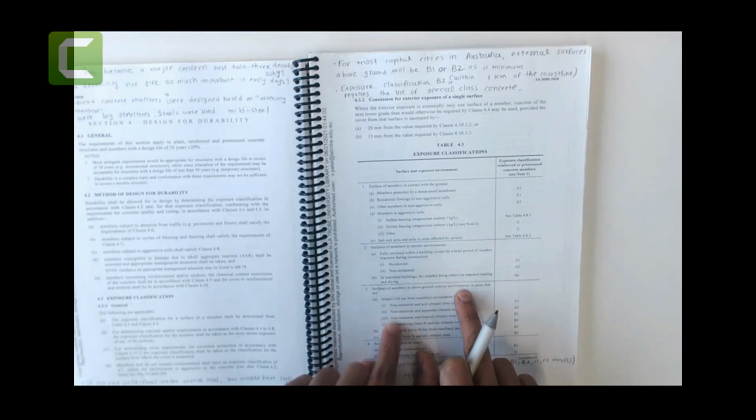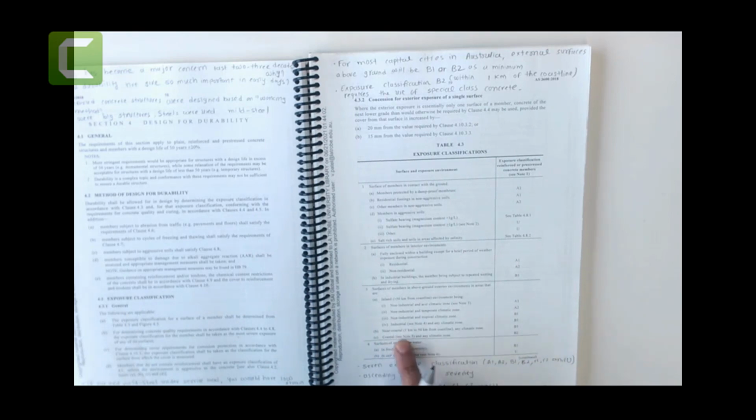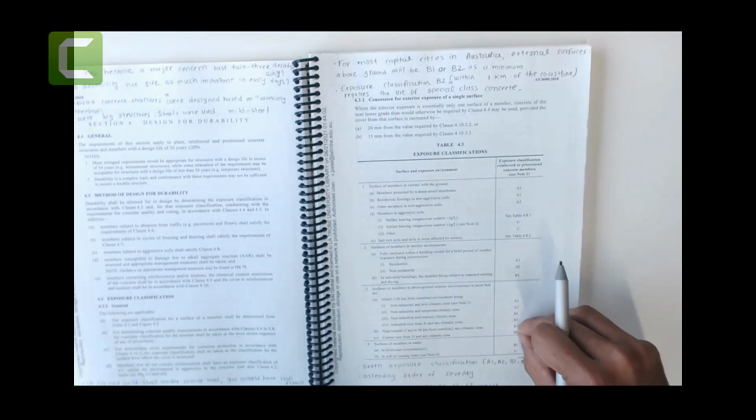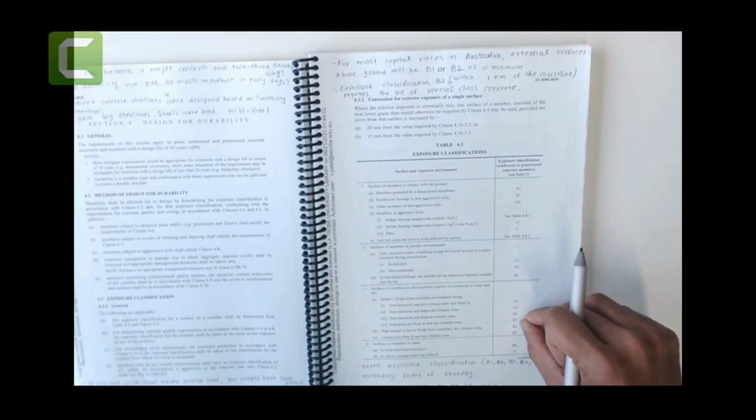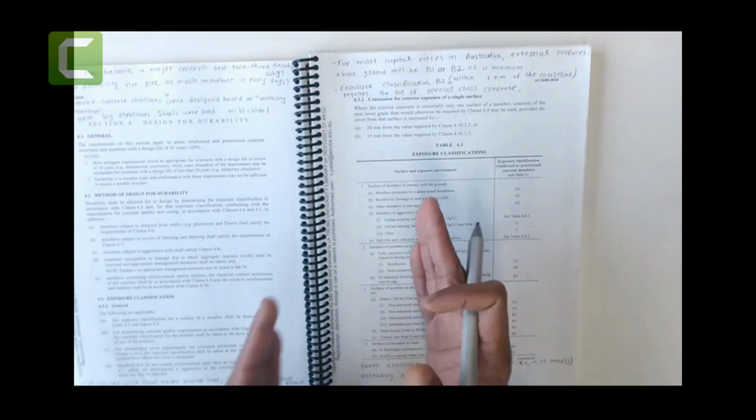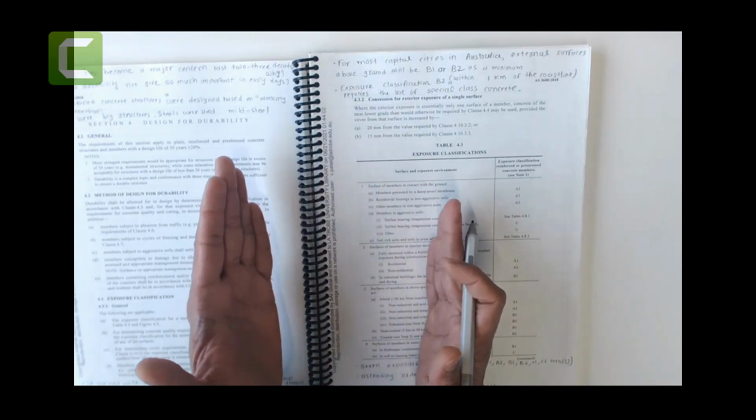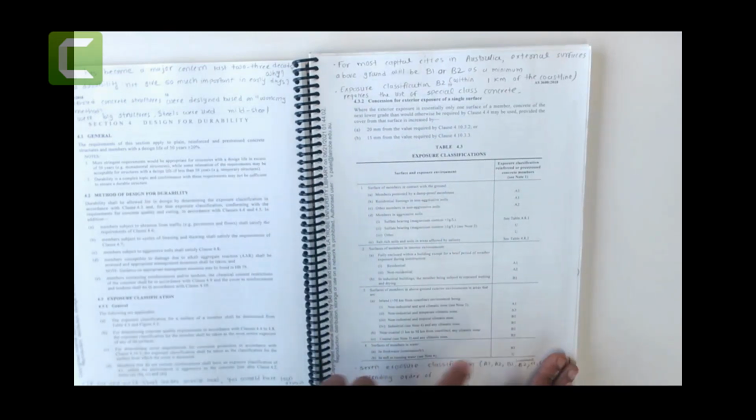For the exterior environment, near the coastline, 1 kilometer to this one, any climate zones, so don't worry about the climate zones. Then I think we just need to go for coastline, see note number 5, because this is near the coastline, and this is on the coastal line because it's 1 kilometer. So let's take it B2. As I mentioned, we are confused between whether we should go for 1 kilometer or we just go for coastline. There is a critical decision to be made here, whether we go for B1 or B2, because B1 says 1 kilometer, so we are on 1 kilometer. If someone just measures it, how do they measure it? So I would go for B2.